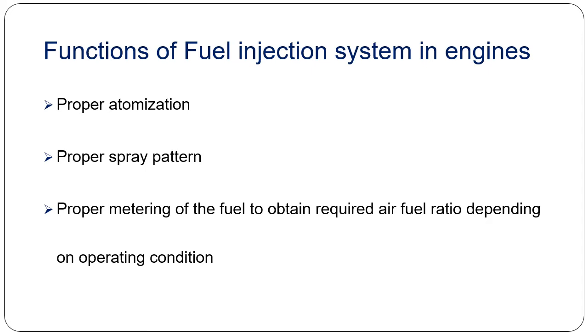One is that the fuel injection system should properly atomize the fuel so that it properly mixes with air. And once mixing is proper, combustion will be proper. Second thing is the spray pattern should be proper so that it covers the total cylinder and the mixture obtained